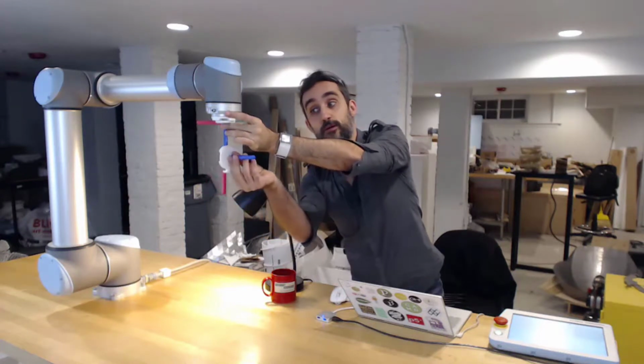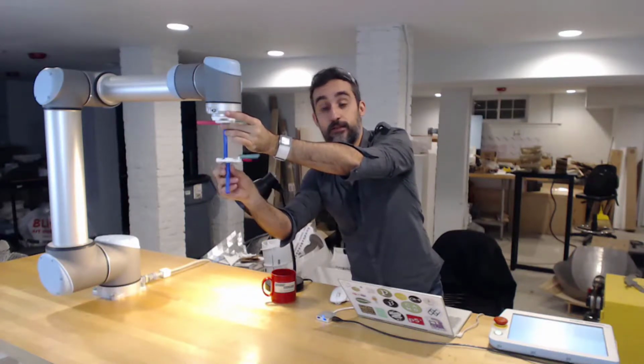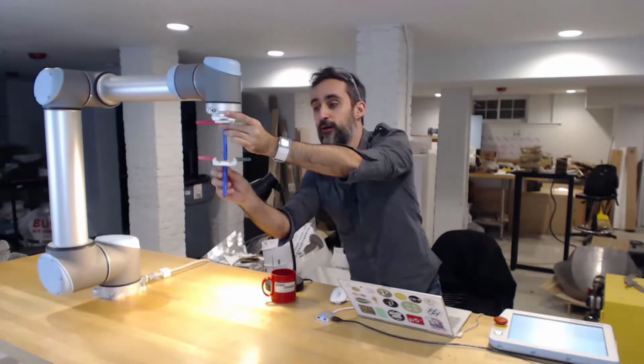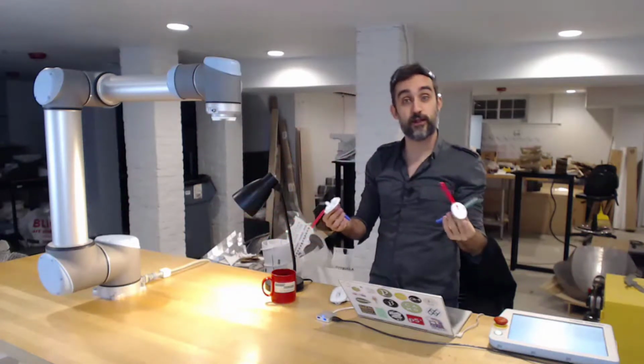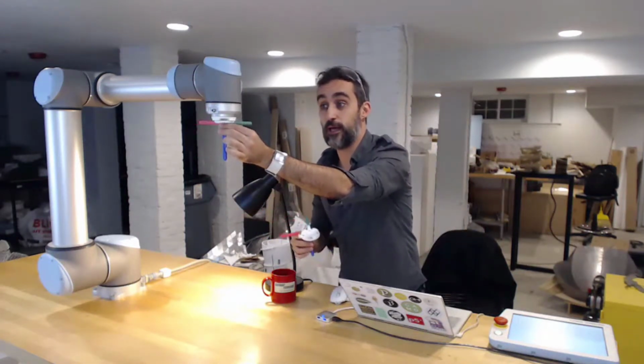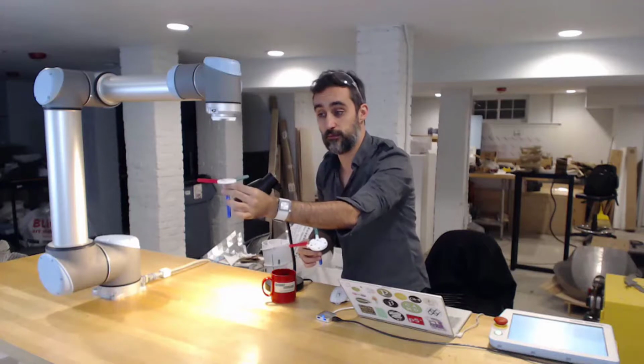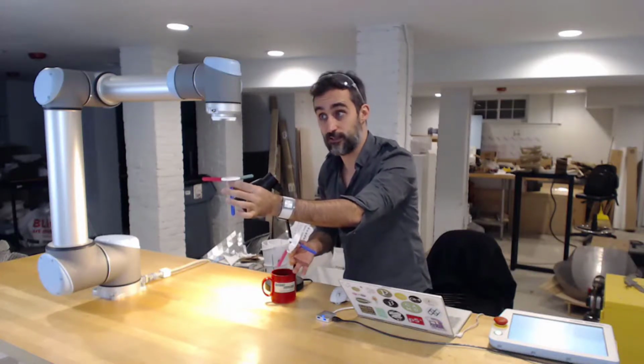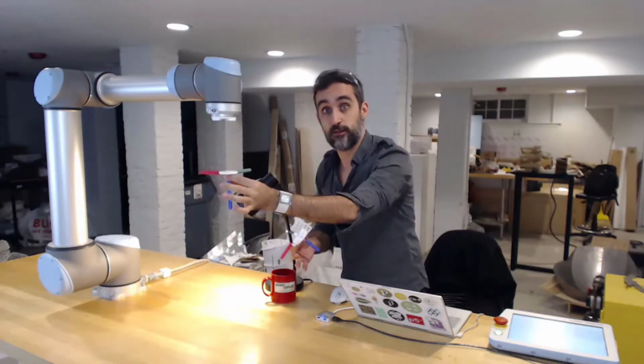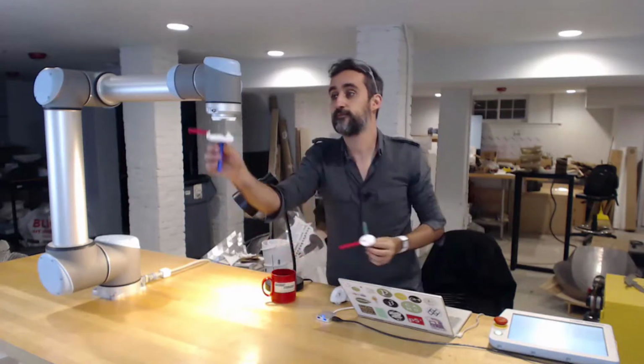And perhaps I want to rotate it if I want to do more complex things, but that's up to you, all right? So the simplest tool that I can define is one where I am moving the TCP a set offset from the base of the flange, right?